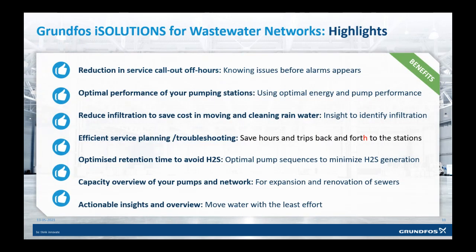All of these things mean that for the utilities, they can reduce their in-service call-out off hours. So we can know issues before alarm appears, deal with them in a more cost-effective way, optimize the pump stations in terms of energy and pump performance, reduce infiltration to save cost in moving and cleaning rainwater, efficient planning, optimize retention time to avoid things like H2S, capacity overview of pumps and networks for asset management, or indeed for pollution prevention, but ultimately providing actions and insights to move the water with the least amount of effort.